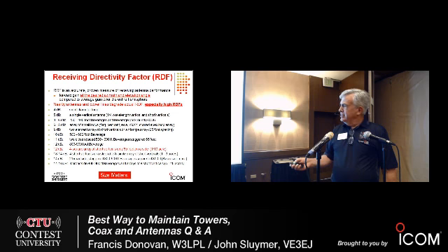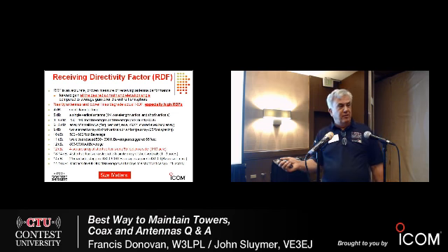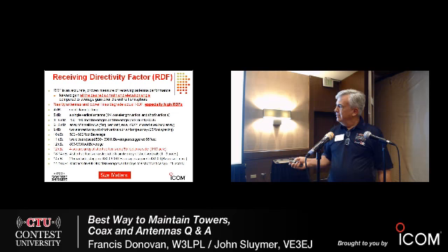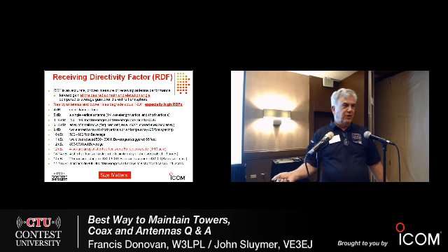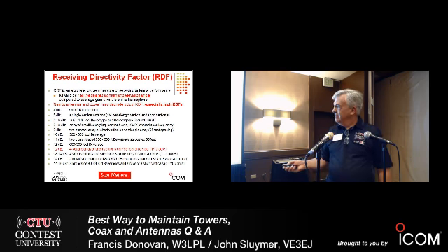Kind of next in line is probably the most popular receiving antenna, mainly because it's been around for 94 years. It was patented in 1920. The Beverage antenna. 500 to 600 foot Beverage. It's just a piece of wire supported typically 7 feet above the ground. Quite high performance and really, really simple.